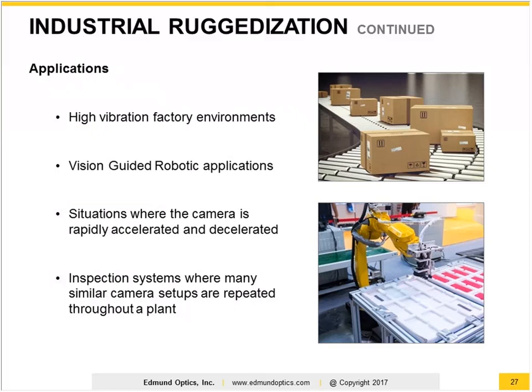The other place would be where you're going to be deploying a lot of cameras under a fixed situation, same focus position, same F number position over and over and over again. You know you're going to do 50, 100, 1,000. You'd be able to actually get your costs down even more by using a product like this. And the nice extra bonus that comes with that, with the simplified design, is that these become more tamper-proof. In many cases, people will go in with the best of intentions to try and make an adjustment to the system to make it work better, but you might have it in a fixed position that's required for you. Removing the ability to do easy focus or easy iris change will allow this system to be much more robust and ruggedized against tampering or changing the system after you've installed it.